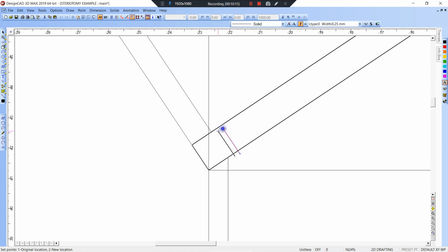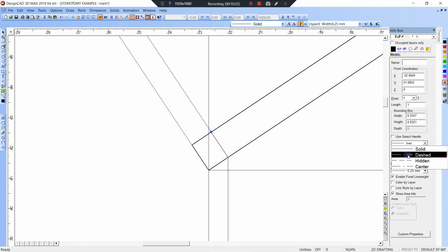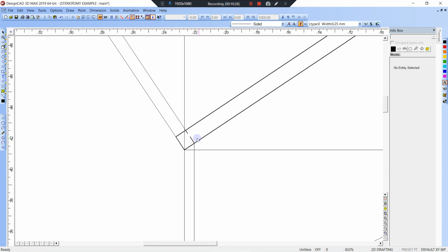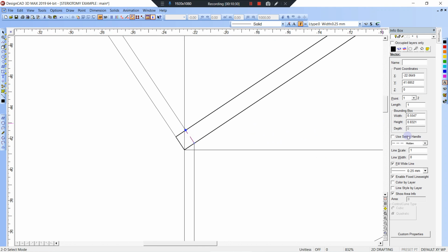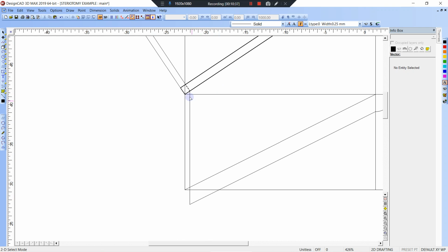This will go there. And let's change it to Control I. Solid, hidden, scale. Let's go scale 1, enter. A little, even still a little big. Alright, so that's this, and then we can transfer that down.